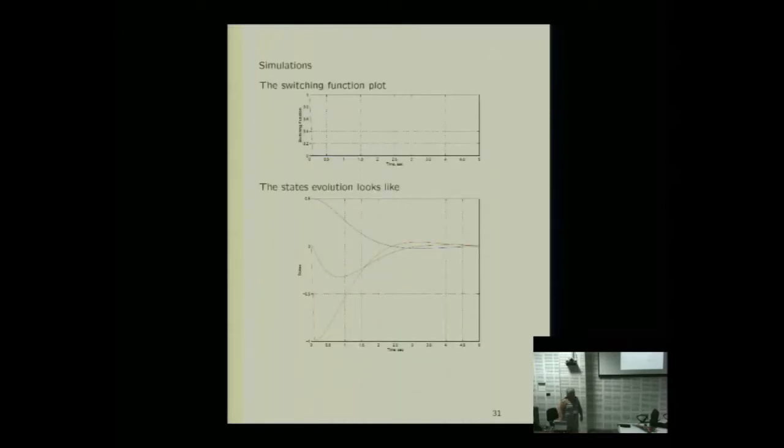And you can look what happens. It's quite hard to see, largely because the switching function plot here is going to 0 very quickly. So by about 0.1 seconds, it's gone to 0. I want that for robustness with that blue line. And we can see this oscillatory poles we've picked give us this system dynamics here. And actually, if we wanted to, we could show that X3 is totally determined by X1 and X2. So this dynamics here is wholly determined by S1, S2, and that subblock, the A11, A12 upper subblock of where the control doesn't act.